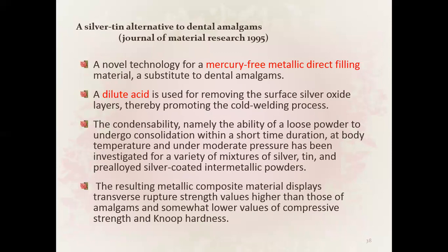Now, a silver tin alternative to dental amalgams. A novel technology for a mercury-free metallic direct filling material, a substitute to dental amalgams. A dilute acid is used for removing the surface silver oxide layers, thereby promoting the cold welding process.